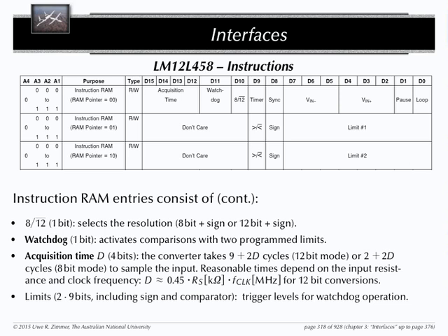And for that, you can use the watchdog limits here. You program two limits, where you can say that if this is above or below one of these limits, then trigger the watchdog interrupt and alert my CPU something is wrong. In fact, if you program this thing in watchdog mode, it doesn't even store the result.